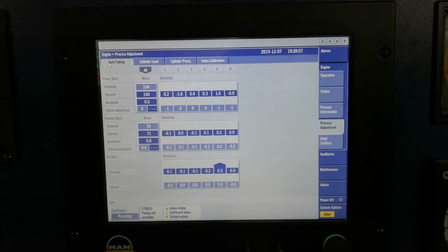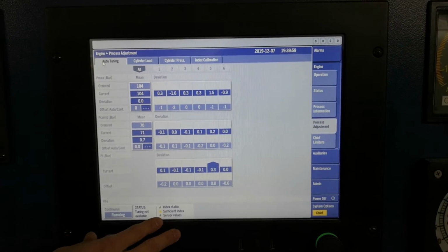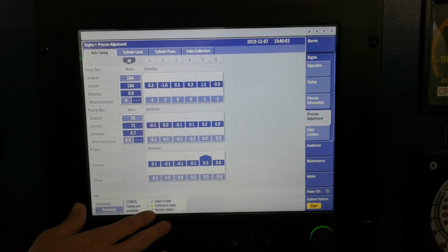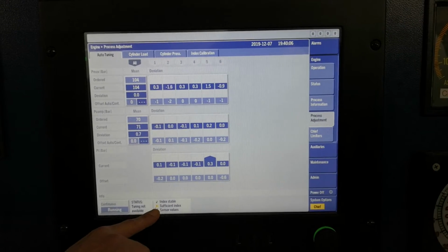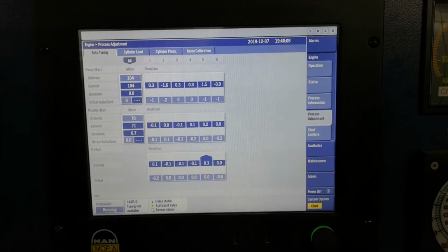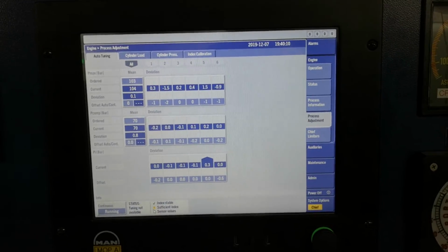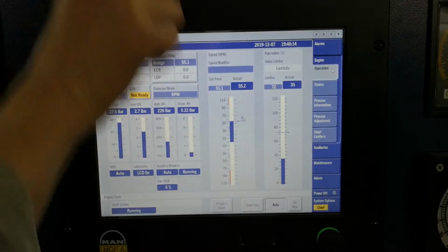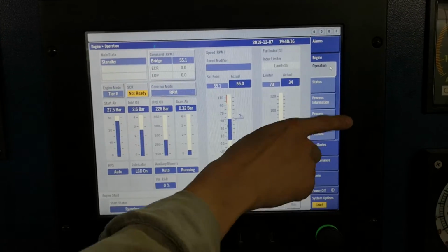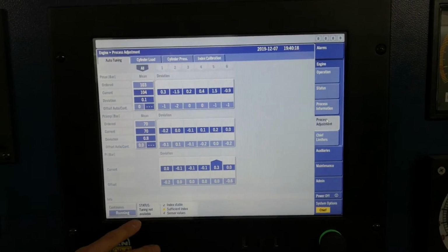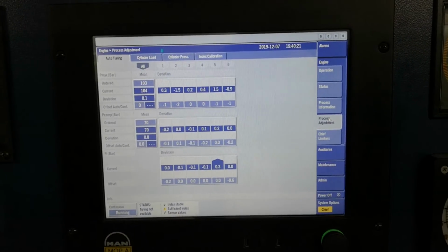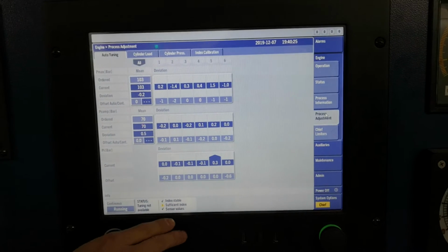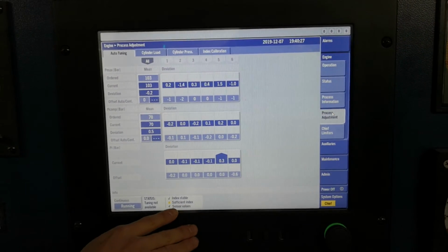That's why. And then these are the 3 conditions which the auto tuning function requires. One of them is this mark, or red mark. It means that now auto tuning is not possible. One is index stability: when the sea is rough and there are too many fluctuations, it cannot function as auto. So in a rough sea we cannot have auto, so we have to adjust manually. If it fails, automatically it stops.